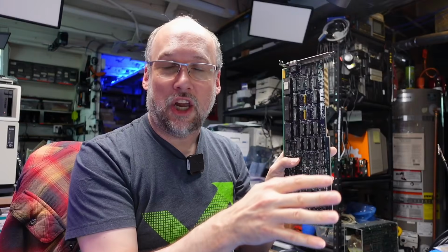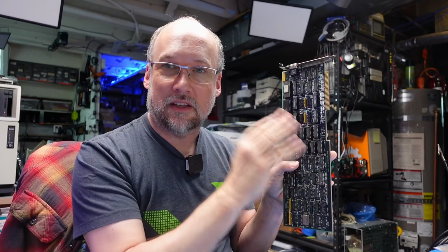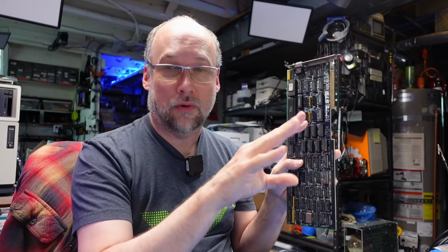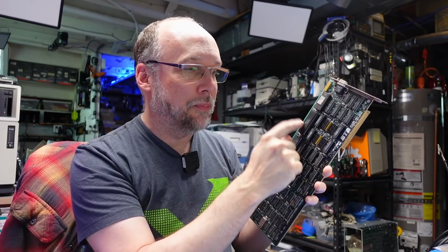And what's really interesting about that is the CRTC itself is what's outputting the horizontal and vertical sync signal to go to your monitor. And as far as the BIOS knows, this is a standard CGA card. When it goes to set it up, it sets it up to output a normal 15 kilohertz horizontal and 60 hertz scan rate. But what you get out of this is not that. You get the 26 kilohertz scan rate at 60 hertz with that high resolution line doubled mode. So that means that there's obviously a bit of trickery happening on this card that takes those calls to program the CRTC and does some translation.